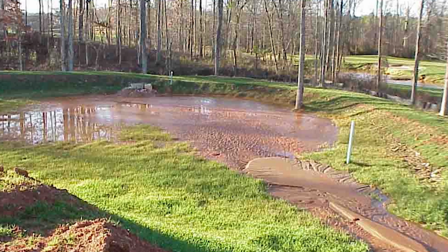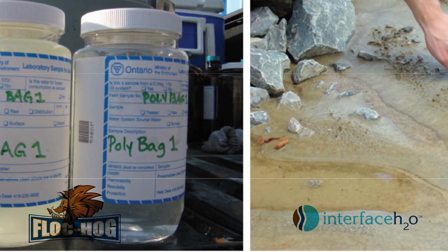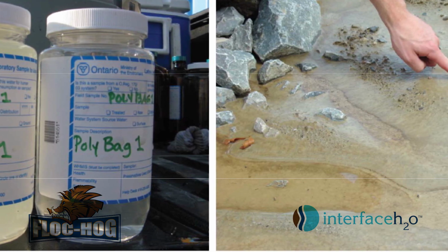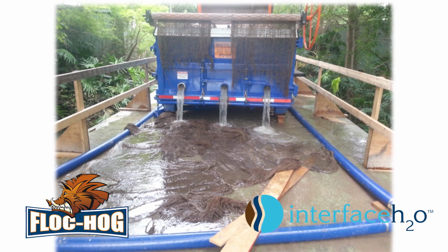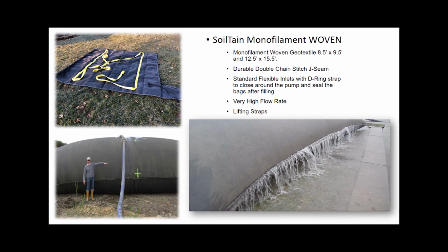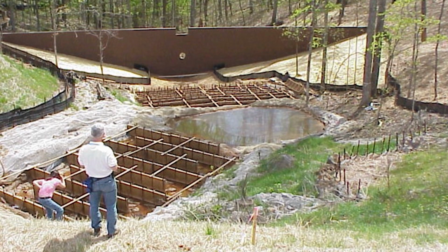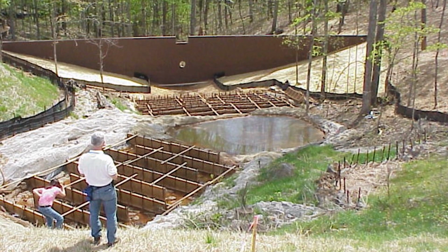How to inspect. Check for site-specific basic soil test report. Ensure polymer type and application rate are in accordance with the soil test report. Check for adequate mixing, settling, and capture. Check for exhausted polymer applications after rain events, during dewatering, and concrete demolition operations. Ensure captured flocs are removed and prevented from traveling beyond the site perimeter.